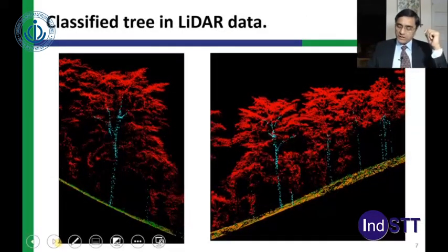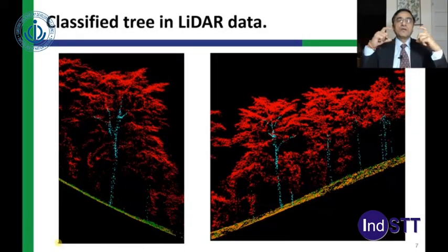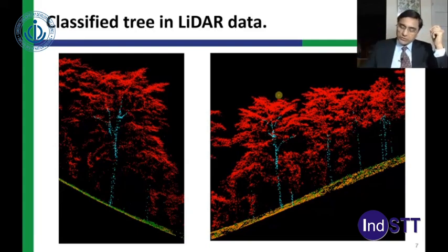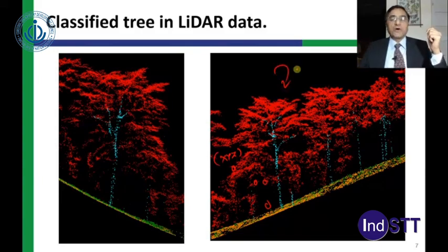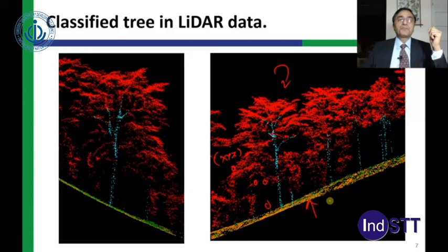What will this data look like? So here is one example. As I said, it's a very comprehensive data, and you will notice this image which I am showing you is in fact made of the coordinates. So wherever there is a point, that means for that point I know its xyz coordinates. So I know the xyz coordinates of all these points along with the points here on the ground. So quite comprehensive data, and with this data, once the coordinates are there, I can now determine the height of the tree, I can determine the slope of the ground, and so on. All the measurements can be done.